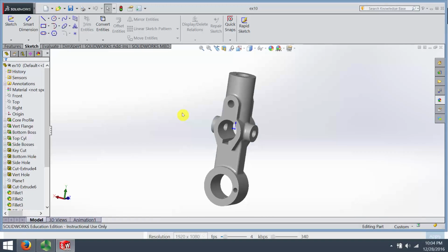And then, in more recent times, a better way to work really is this idea, and I use it constantly, this top-down assembly modeling. The idea that's different is instead of just making individual parts and modeling them, you can model some of the parts as you need to or as it's appropriate within the context of the assembly. And so, looking at this hole diameter, or the location of this hole center to center to this hole, you can capture those pieces of information just so easily, and you can much more often guarantee that you're going to have parts that fit together. And that's really where the value of this comes in.